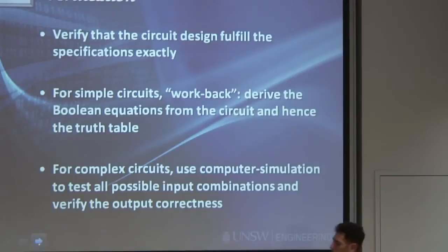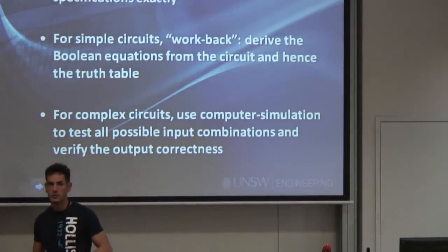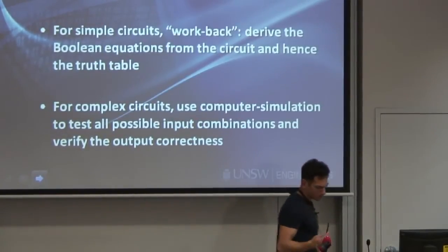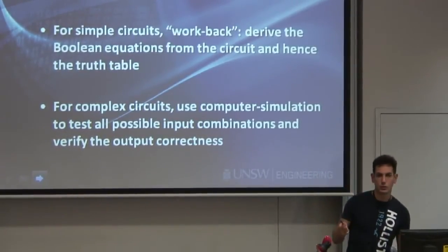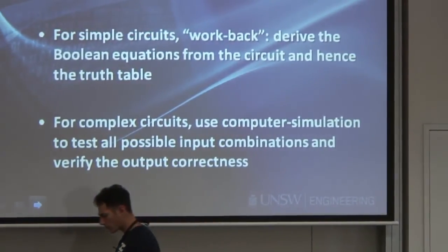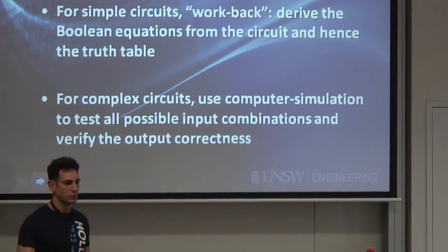Now, if we do have more complex circuits, and in reality the circuits will be more complex than just this, usually we'll use computer simulations, and these are the kind of stuff you do in your lab, where you'll write a test bench Verilog code that will run all the possible inputs to our circuit.